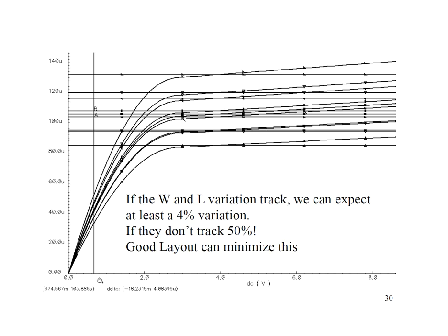So if we sweep a DC input and we're stepping current here, you can see that there's a region of relatively flat current. But just in this plot, I'm changing W and L, right?